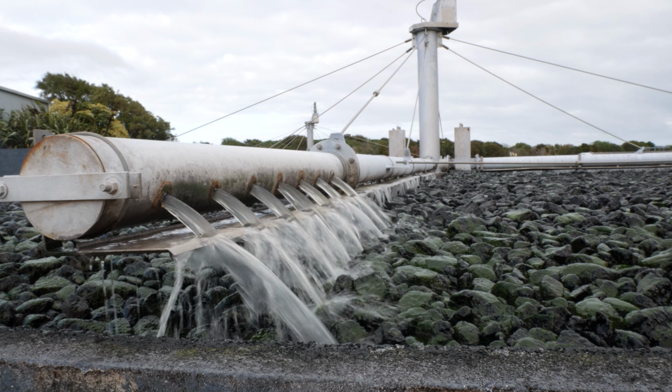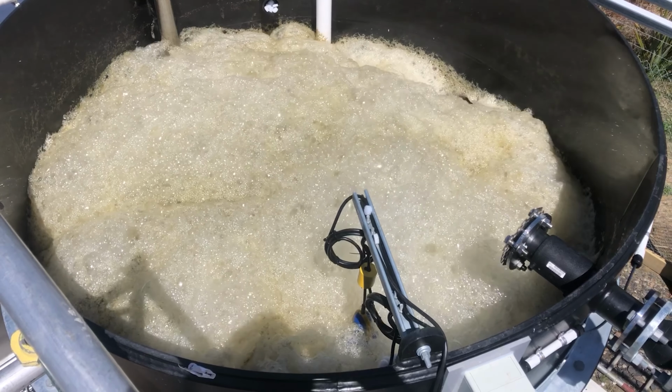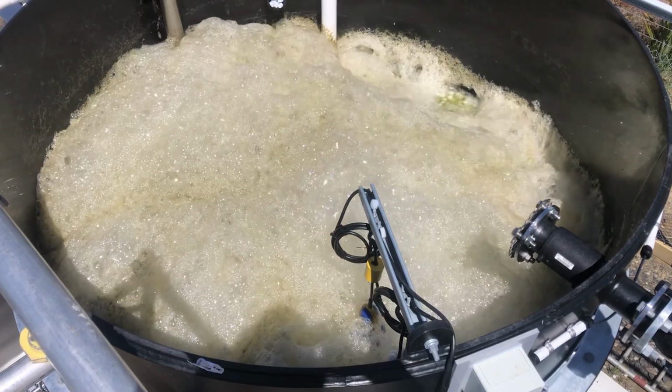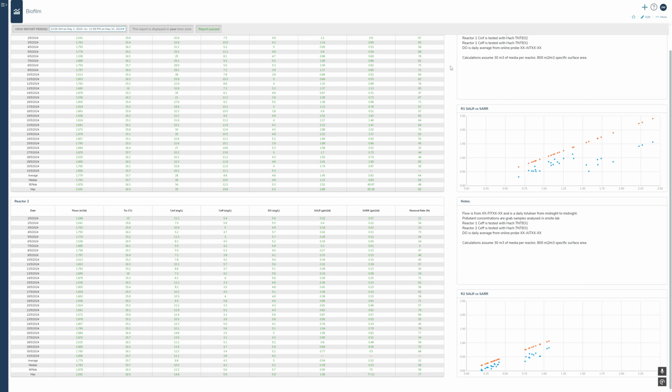Yeah, so for a wastewater plant, we can look at basically a biofilm system. So if it's a trickling filter, or it's an MBBR, or it's an MABR, or RBC, any of these biofilm systems. If you consider nitrification, we can look at the ammonia loading onto the system. And if you're just looking at data, you can say, well, you have a flow in milligrams per liter, and out is flow in milligrams per liter. And that tells you a certain picture, but we can then look and calculate what the kgs per day into the system and the kgs per day going out is.